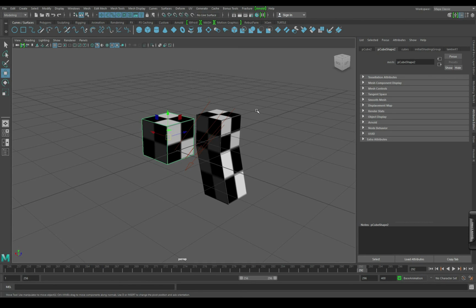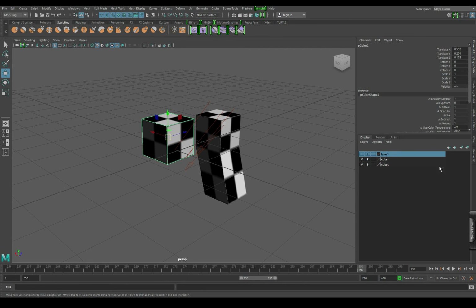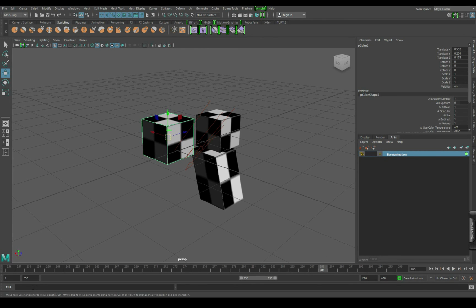It's massive. It's a huge program, but at least you shouldn't be that confused now with, okay, so these are my menus, these are quick sets, these are just tools above here for my rendering and stuff, my tools to move, rotate, scale, my different viewports, different layouts to help me in a specific menu, and your attributes and everything over here, which we will go into properly, you know, layers, hiding things, rendering, animation layers, etc. Your timeline and your little MEL script commands where you can put them also in here. Boom. You can put all your scripts in here or here.